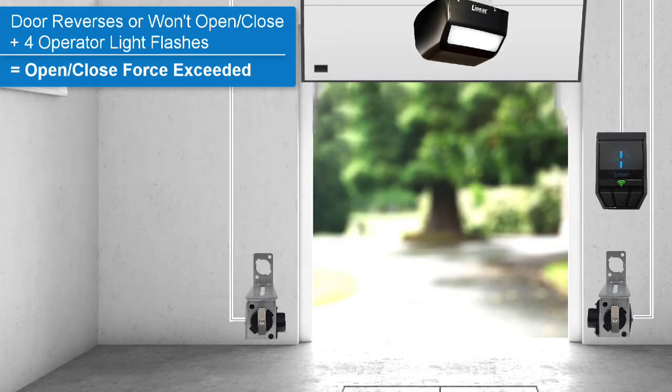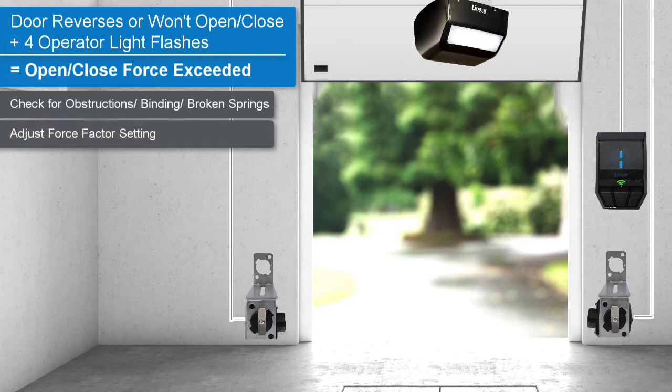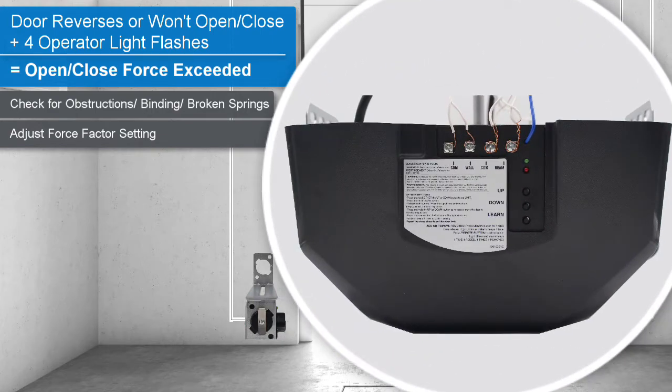To fix this issue, first check for any obstructions or binding of the garage door. Also look at the door balancing springs to make sure they're not broken. If you don't see any obstructions, binding, or broken springs, adjust the force factor setting. To adjust the force factor setting, first locate the force factor programming buttons on the back of the operator. Your force factor settings can be adjusted using the up, down, and learn buttons.